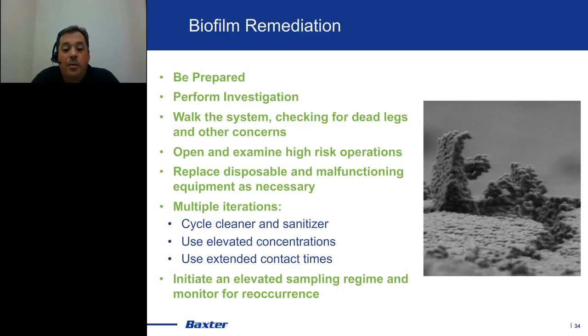Then after that, you're probably going to need to come in with a multi-iteration cleaning sanitization process where you're going to cycle cleaner, sanitizer a few times. And then you're going to need to make sure when you do it, you're going to be at elevated concentrations and elevated contact times. That's really what it usually takes to be effective. So that's kind of the treatment measures.